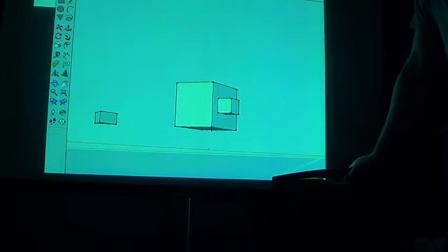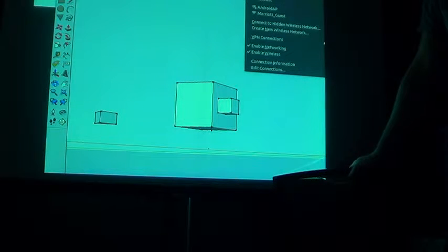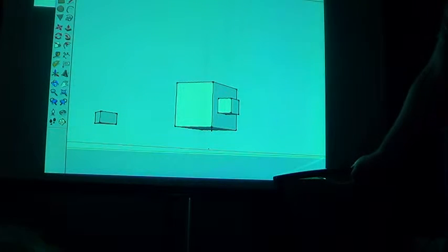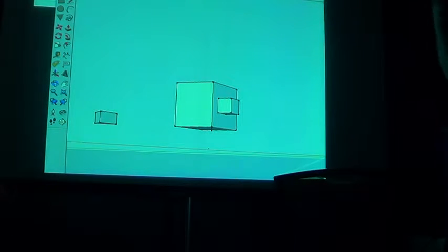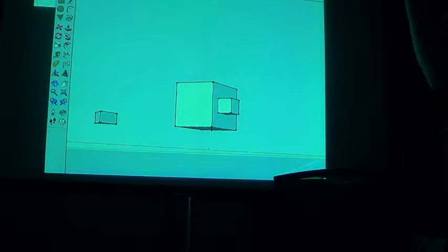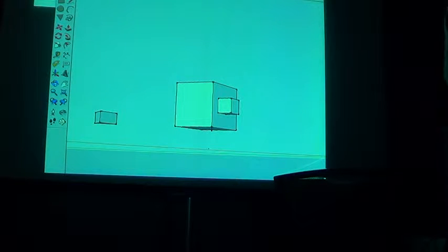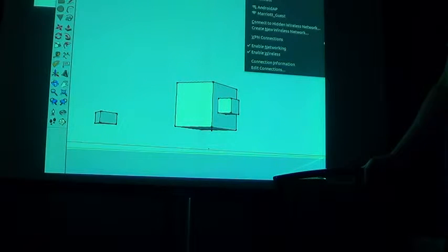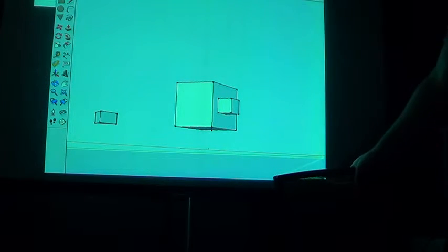So then on a multi-nozzle machine, couldn't you print the supports in something water soluble and then just... Yep. And a lot of the slicing software supports that. You tell it you have 2 nozzles and the second one will be used for support. Most of the time when you do that, you're letting the slicing software build the support for you. So if you build the support into your model, you have to be able to break it apart. So you're actually feeding the slicing software 2 models and telling it that the second model should be printed at this offset with the second material and the second nozzle at the same time, and then it'll know to go back and forth and change which one it's printing with. So you can do that. It's usually easier to let the slicing software deal with it.